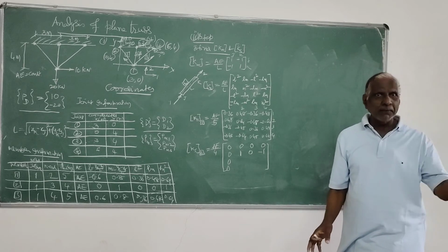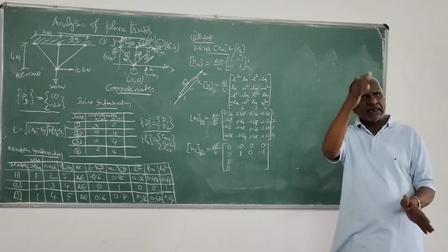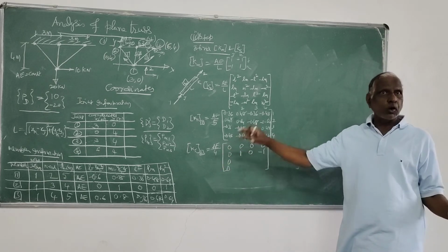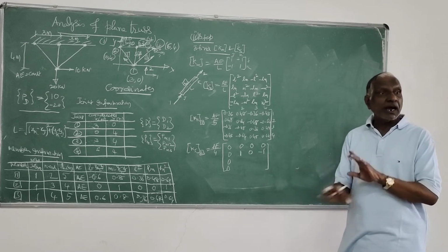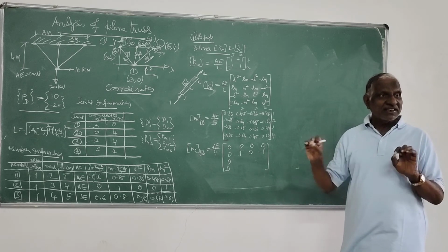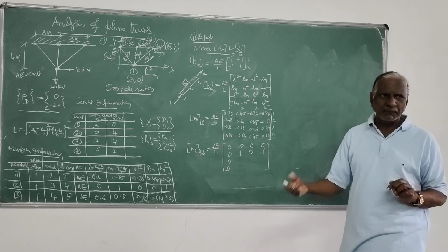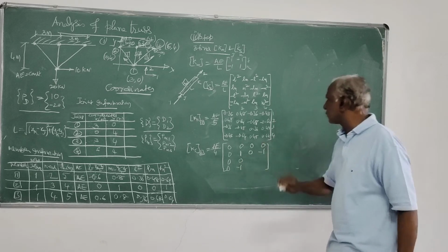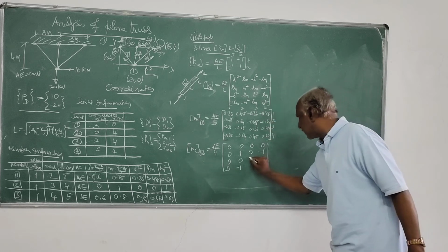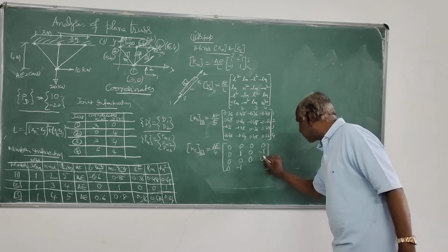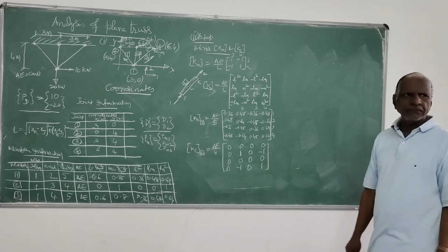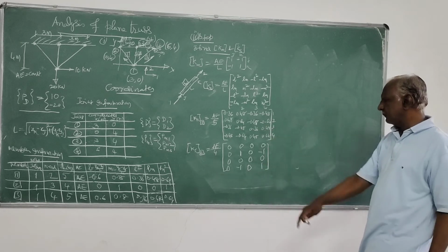That's the reason why in beams and frames you are matching that stiffness matrix. We didn't separate like this, global and local and all. Here we have to separate it. It is a different approach, called element approach. Then here also it is 0 minus 1. Then this is L square 0, Ln 0. It is 0 here. Here it is m square 1. So this is for member 2.